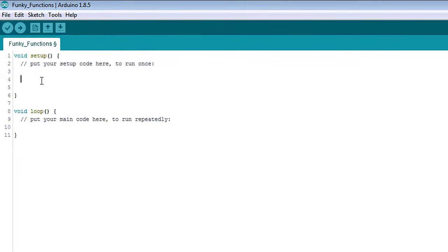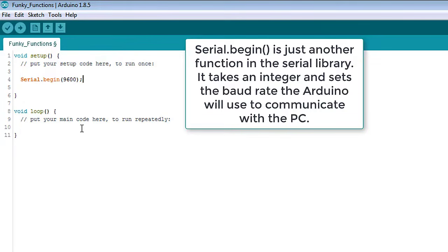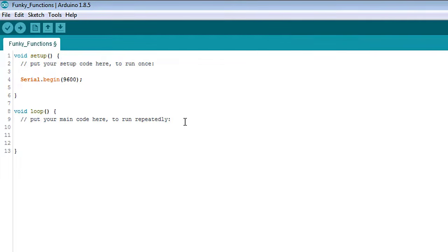Now let's dissect an example function, Serial.print, and talk about the different parts. We're going to use the following code snippet, which I'm going to type here right in front of you, and focus on the function. So let's start this with Serial.begin here in setup, and then let's jump over to loop and type Serial.print, which is the function we're going to take a close look at.